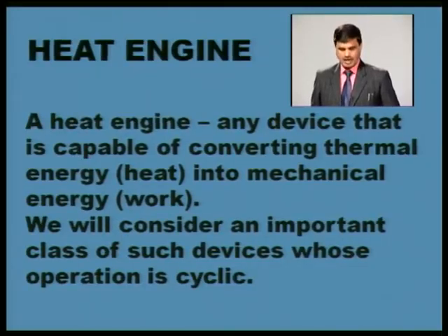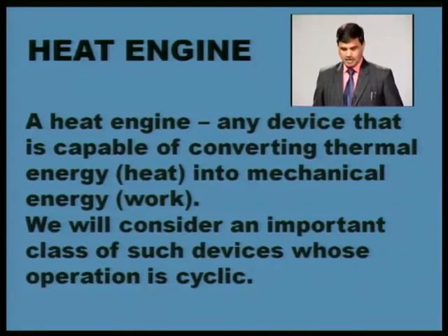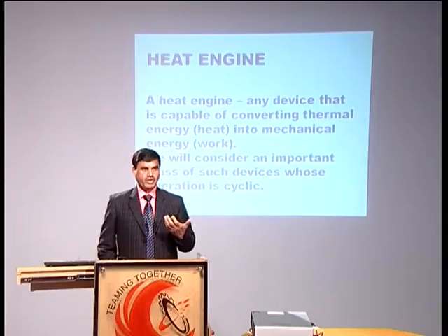Heat engines are in the category where heat, which is a low grade energy, is given as input to the engine, and the engine converts that heat into mechanical work, which is high grade energy. There is a difference between heat and work. Both have the same unit, joules or kilojoules, but their level is different. When I say low grade energy, it is heat. When I say high grade energy, it is work. Low grade energy is getting converted into work, that is high grade energy.